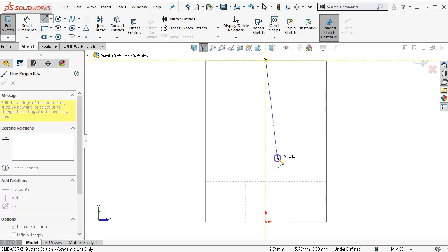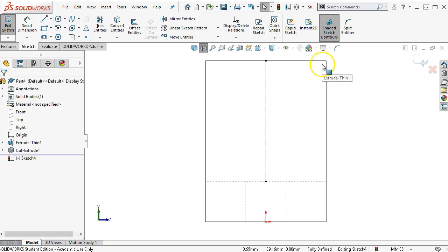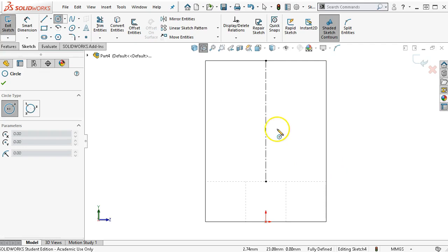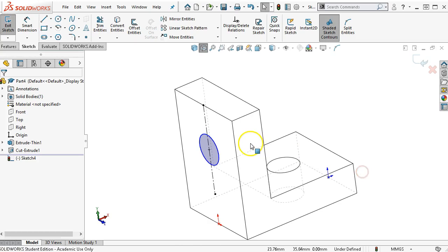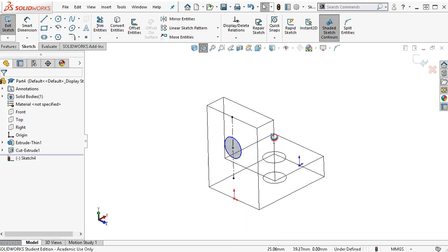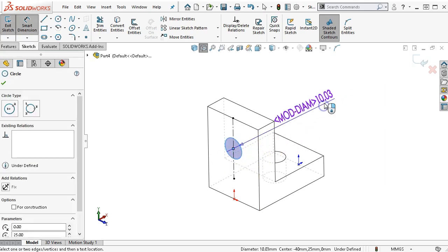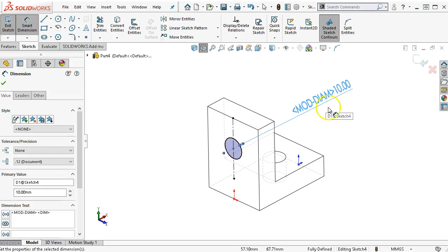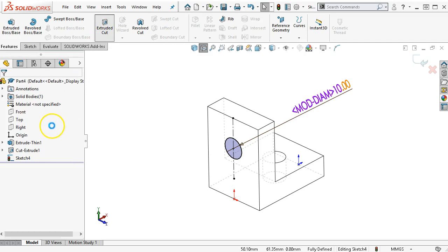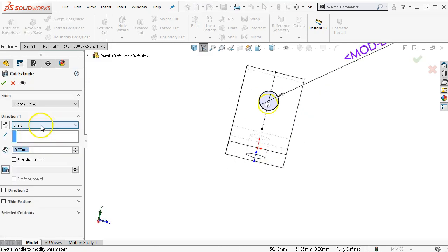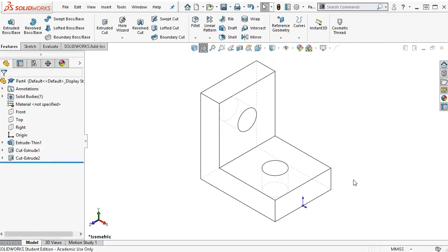And then I can find the midpoint. Oh, I picked it, but it did not start the line. And then if we went midpoint to midpoint as opposed to corner, we end up with the same net result. But the perception is still that I'm on the back, which is always interesting to kind of get if that gets flipped around on you. So 10 millimeters, and we'll go ahead and extrude cut that through. Alright, so that gives me the L bracket.